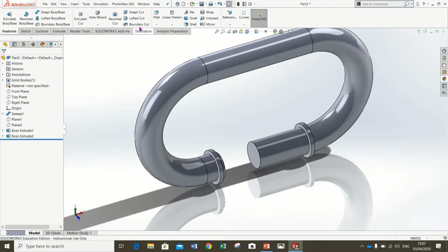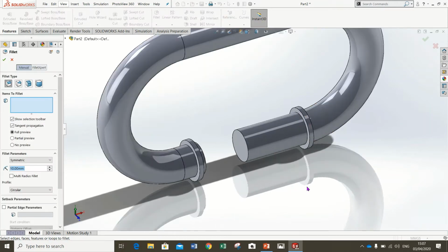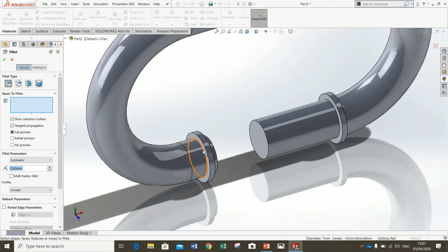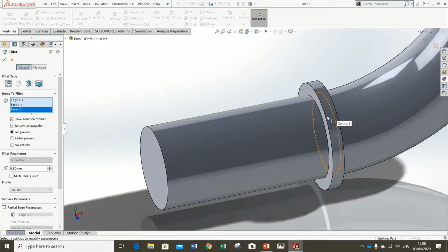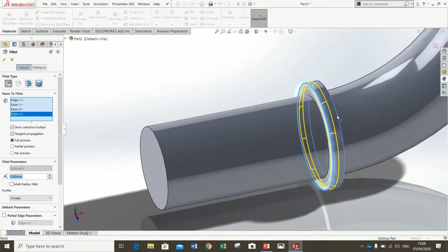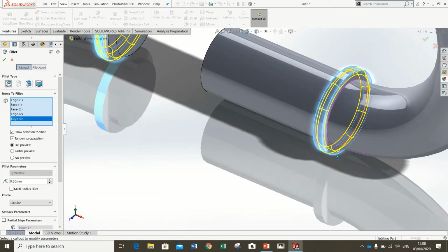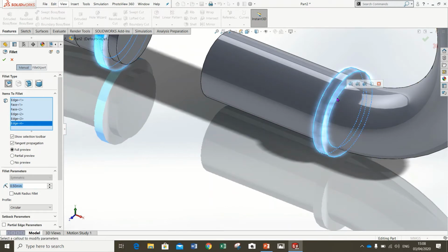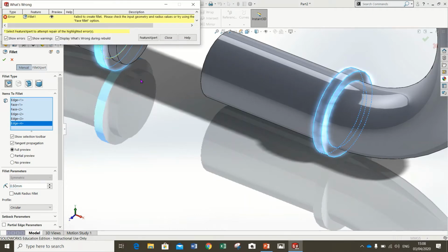Alright, actually what I'm going to do, I'm just going to fillet the corners of these guys. You can see here, I'm going to fillet. Be careful what you're selecting. Now it's automatically set default here to 10 again, so I'm going to go 0.5, and I'm going to select a few corners around these little collars that I did, just to round those guys off. Now you can zoom in if you want to make sure you have the correct circle. And I'm just going to get the back of this one here just to make it more aesthetically pleasing. Okay, you can see the fillets listed here. I'm going to accept that. Sorry, it's thrown up a problem there.